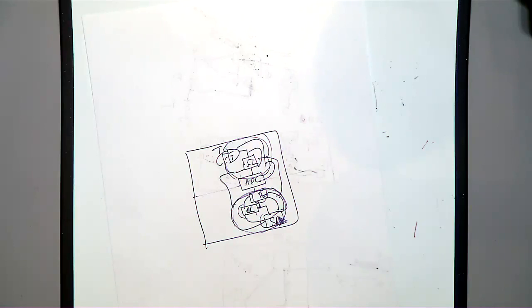When you design your PCB, pay attention to where the current flows. Many problems with mixed signal PCB, mixed meaning both analog and digital, can be avoided by following this simple advice. Pay attention to where the current flows.